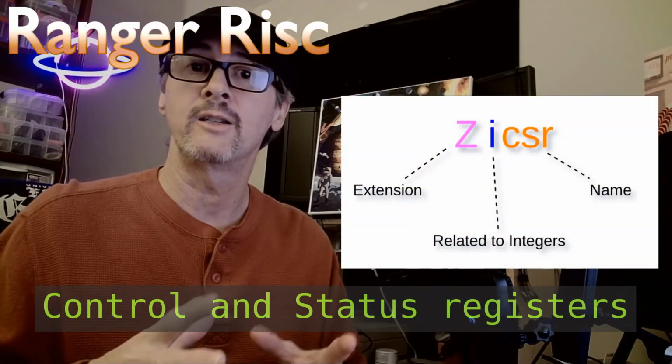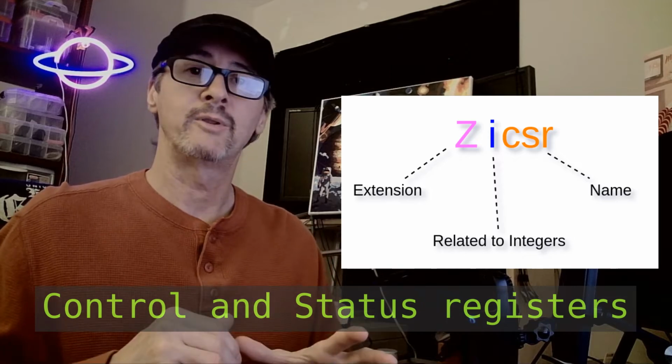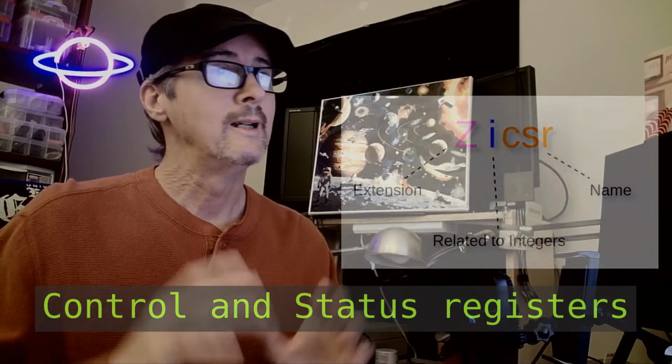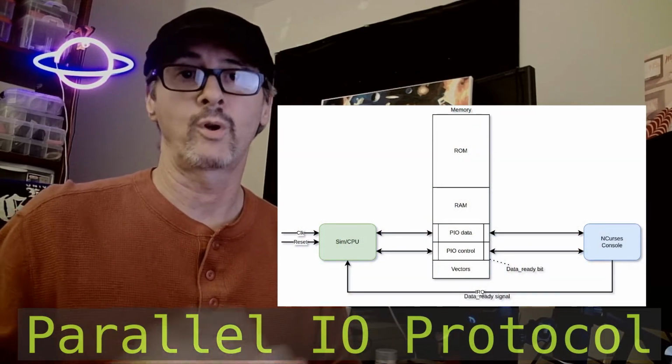In a previous episode, we introduced ourselves to the ZICSR extension, otherwise known as the CSR instructions. In this episode, we implement and make use of those CSR instructions. Now, there are many ways to implement CSRs because there are a lot of them, but as such, we are implementing only a bare minimum of them in order to support a very simple parallel I/O protocol.